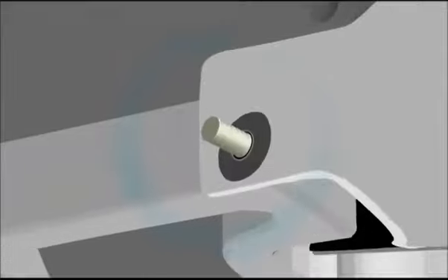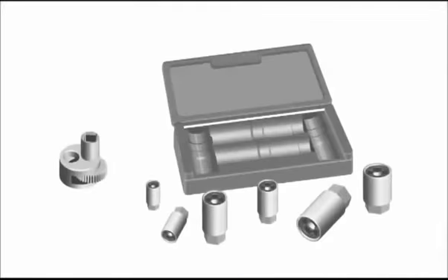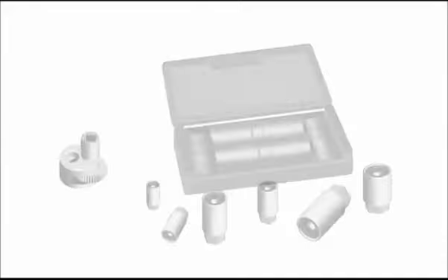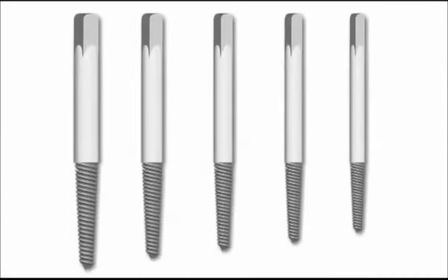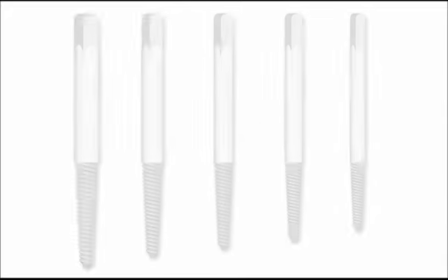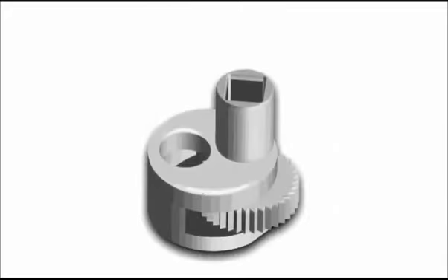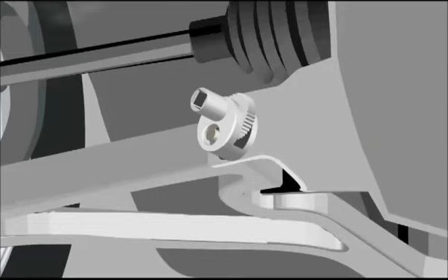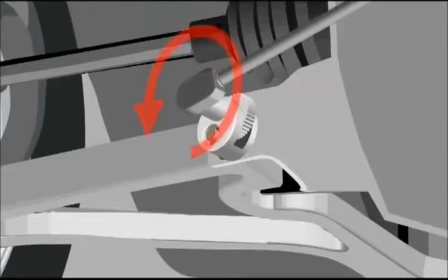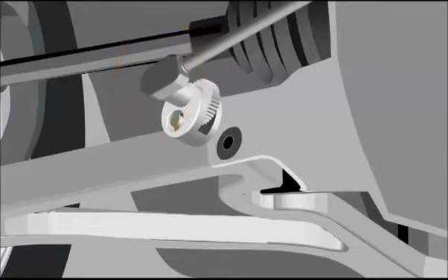Occasionally, you may need to remove a broken fastener. Several tools are available to aid you in doing so. Stud removal tools, left-hand drill bits, and extractor tools can all be used depending on the condition of the fastener. If the broken fastener you are trying to remove has enough shank exposed, then try a cam-type stud extractor to remove it. Place the broken fastener through the hole on the tool and, using a ratchet or breaker bar, turn the tool in the direction the fastener needs to be backed out. This will cause the cam to tighten against the fastener and then allow you to back the fastener out.